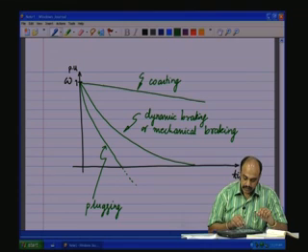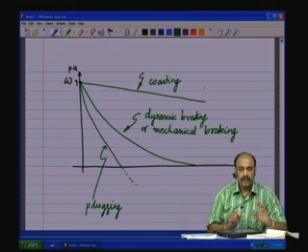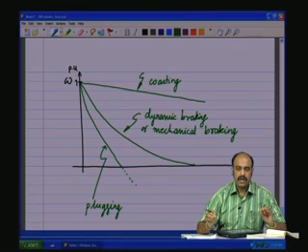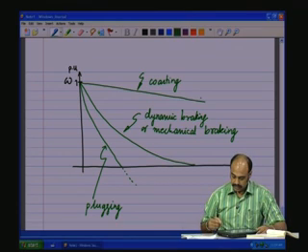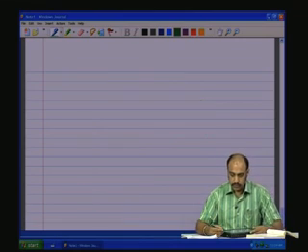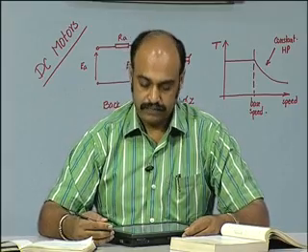And in the case of coasting, it is slowest. There is no control on that except that it will go to 0 due to the energy which is lost in the bearing friction, windage and things like that. So, that can take quite a long time if the load inertia is very high. So, that is about the braking.